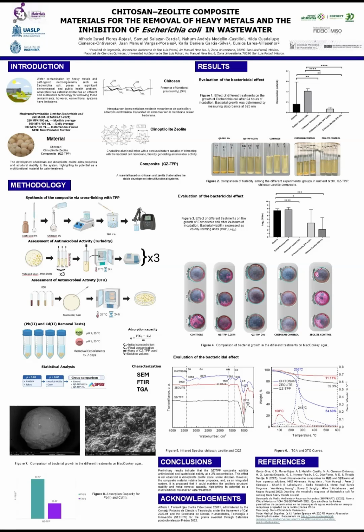Lead and cadmium removal. The maximum adsorption capacities for lead were 77.17 milligrams per gram at pH 5, while for cadmium, values of 30.07 milligrams per gram were recorded at pH 7. The pH values studied were selected based on the aqueous speciation of both metals, avoiding precipitation conditions, in order to ensure the presence of the cations in solution.